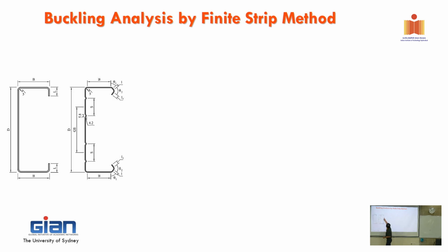So if you fold this lip in here, you give a stiffer lip, and then it will help for distortional buckling. All right? So it means that it's helping. So in that particular cross section, it actually helps local buckling and distortional buckling.